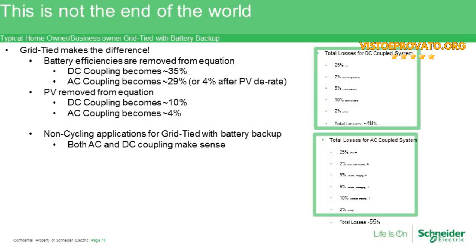In particular, it could be that a grid-tied system is a more efficient way of doing it over the long run. So we're not talking about 2 or 3 years, we're talking about 10, 15, 20 years, that with daytime air conditioning that's very consistent, we're going to be able to offset that more. So is there a big difference between a grid-tied system and a battery-based system? Yeah, there could be. That 98% efficiency versus, say, 85% efficiency for a battery-based system could come into account here.